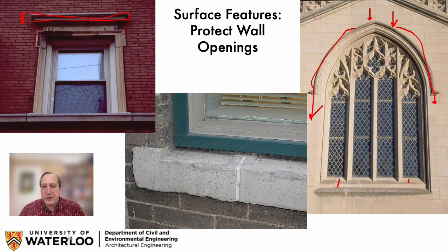Steeply sloping windowsills. This is not a place where rainwater sits, so that it can find any kind of crack and opening to get into. It's shed off the building as quickly as possible. And in the middle here, you can see this is a building that happens to be in Kansas, where pre-made window sills with recessed gaps make sure that when you mortar these pieces together, the most sensitive bit, the mortar joint, is kept up out of the water, so that water that runs off is encouraged immediately to run into this and then out and away.